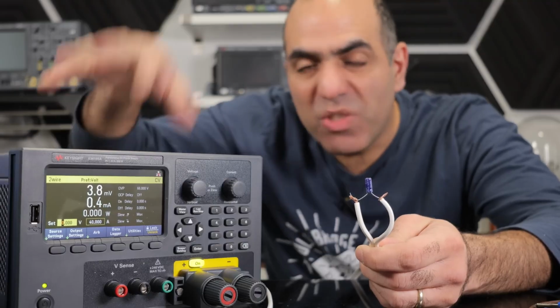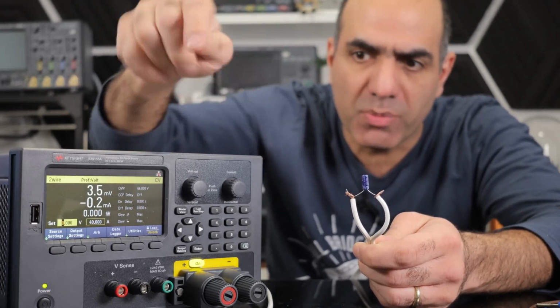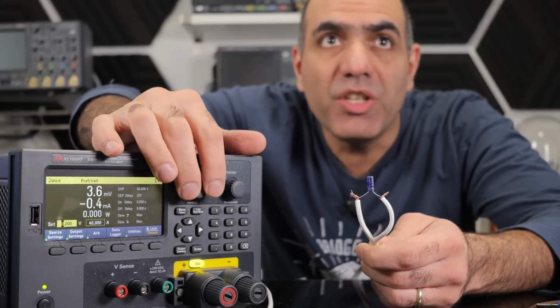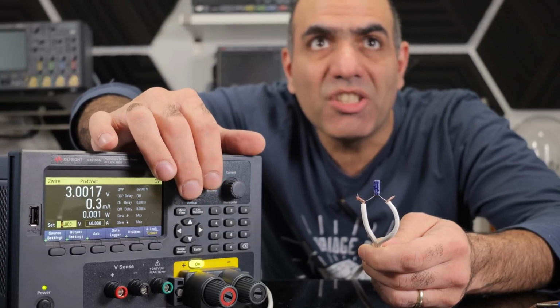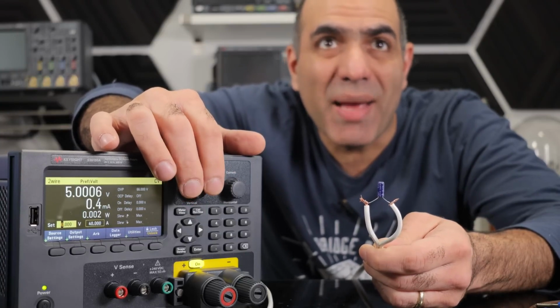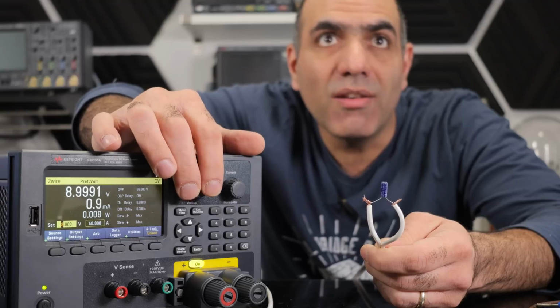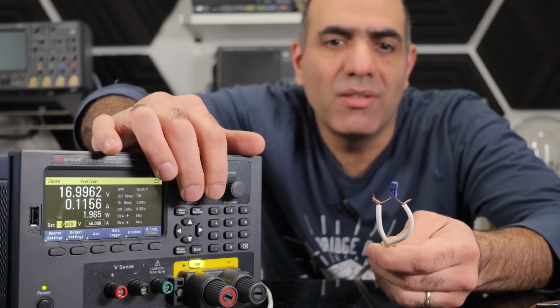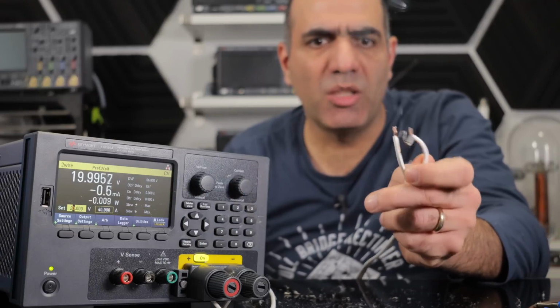I have a brand new 60 volt 40 amp power supply and my capacitor is rated for 16 volts, but I place it in reverse polarity, and if I increase the voltage, at some point it starts conducting current and the capacitor will slowly heat up. You see? Oh, there you go. It's starting to conduct. It's almost 1 watt through the capacitor. Oh, I didn't even see it bulging.